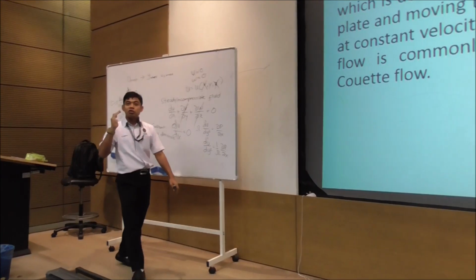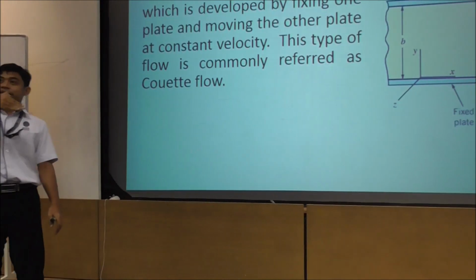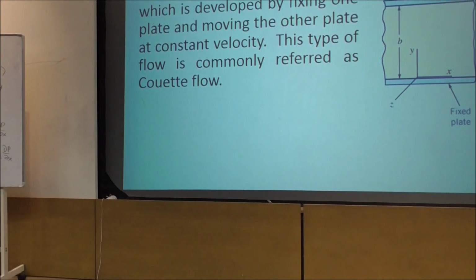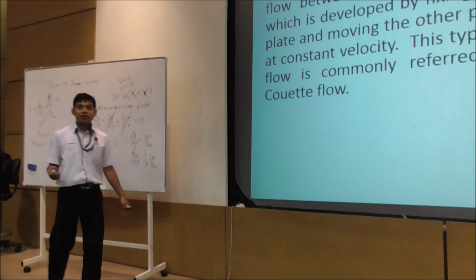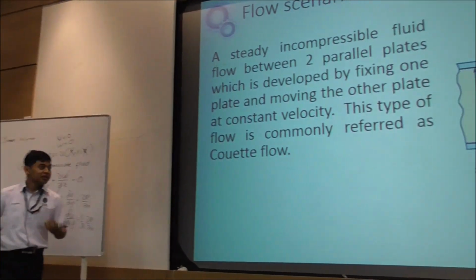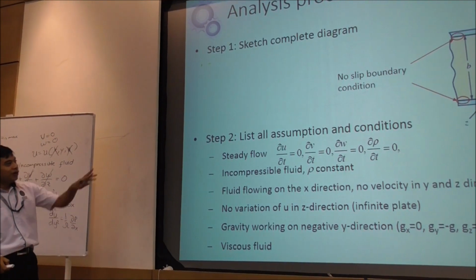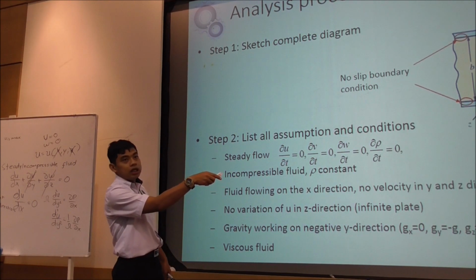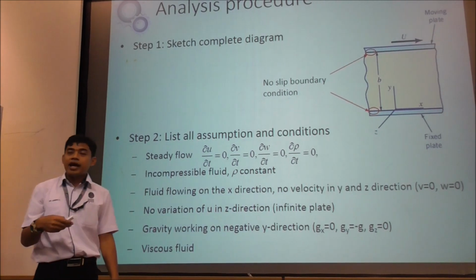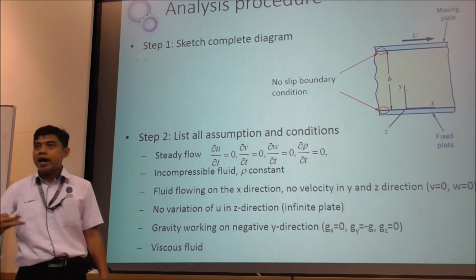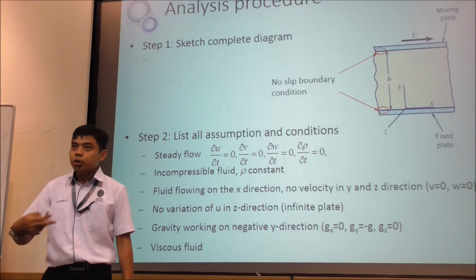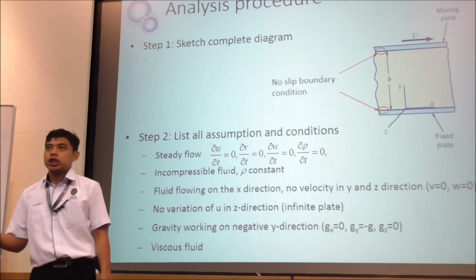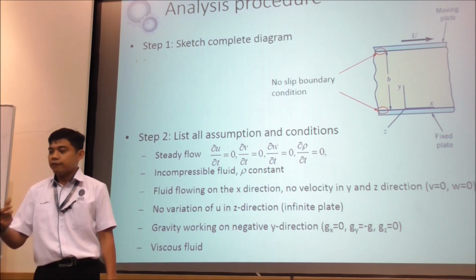If you change your top plate, rather than stop, it's moving. When you have that, don't get nervous. It's nothing. If you look at the condition now, the only change is the boundary condition. Now the boundary condition, rather than having u equal to 0 at y equal to h, you have u equal to big U at y equal to h. Clear? So that's the only difference.